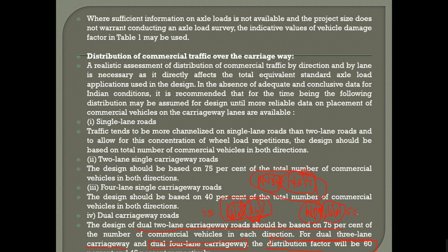And when you see additional lanes, from 6-lane to 8 lanes, 2 lanes have been added. So the commercial vehicles distribution factor has reduced to 45.